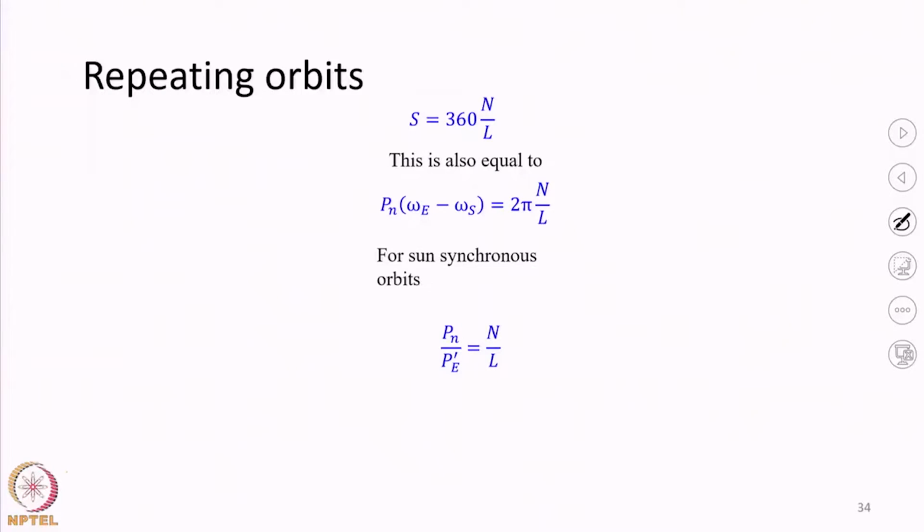But still we can put a satellite with 3000 kilometer swath, it is possible, but normally we will not do it, in order to maintain the geometrical consistency of the image, except for very few sensors like MODIS, AVHRR, VIIRS. Most of the satellites in near polar sun synchronous orbit have a swath width of only hundreds of kilometers. So, this is again to drive home the point, the longitudinal shift is given by 360 n by L.